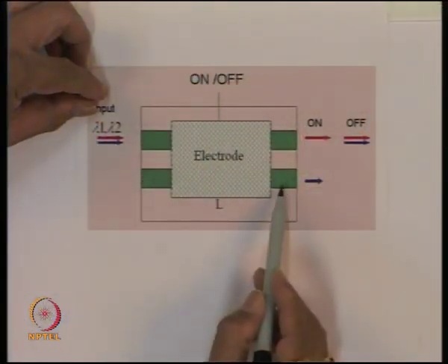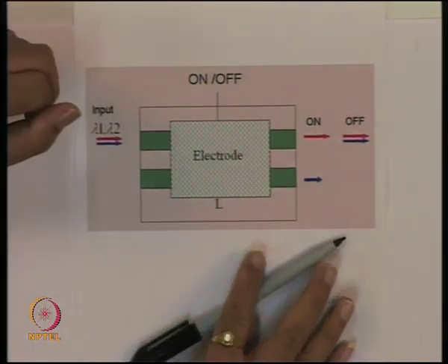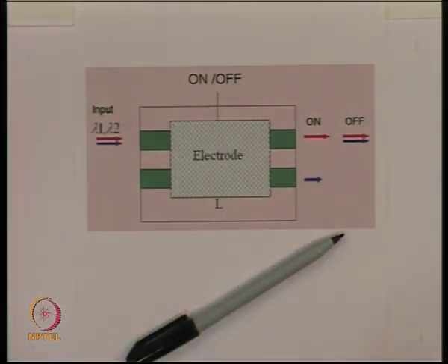dependent dropping device. So the signals were coming which are flowing on this. Essentially by applying a control signal, one of the wavelengths is dropped at this location. So in a complex WDM network where large number of wavelengths are moving, if you want to drop a certain wavelength at a certain destination, we can introduce this device, apply the control signal in such a way that that particular wavelength can be dropped at the junction, and essentially we have created a wavelength drop multiplex.